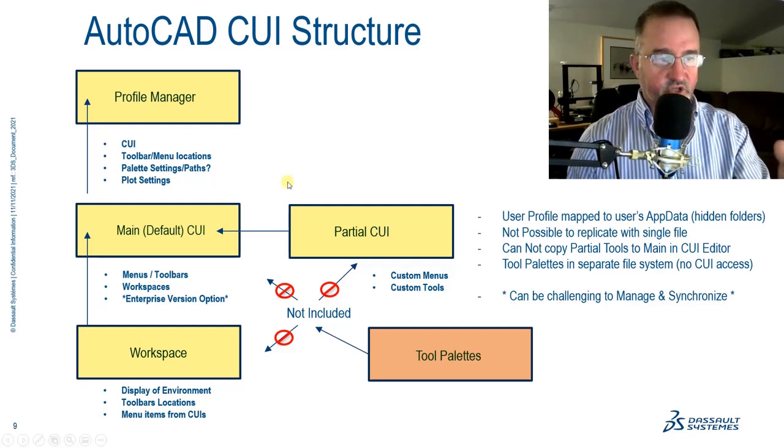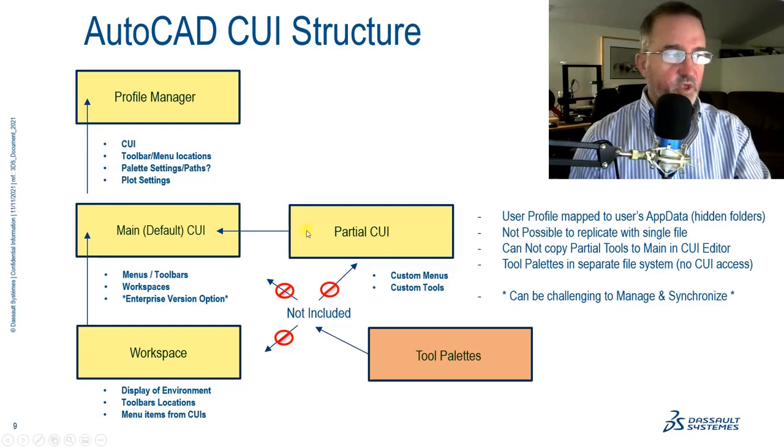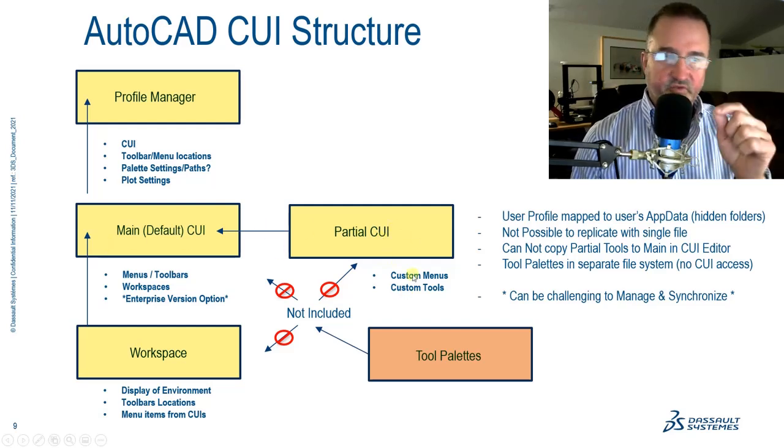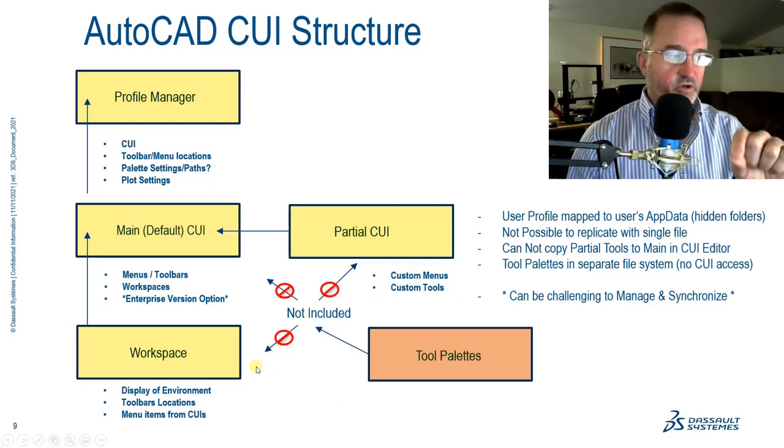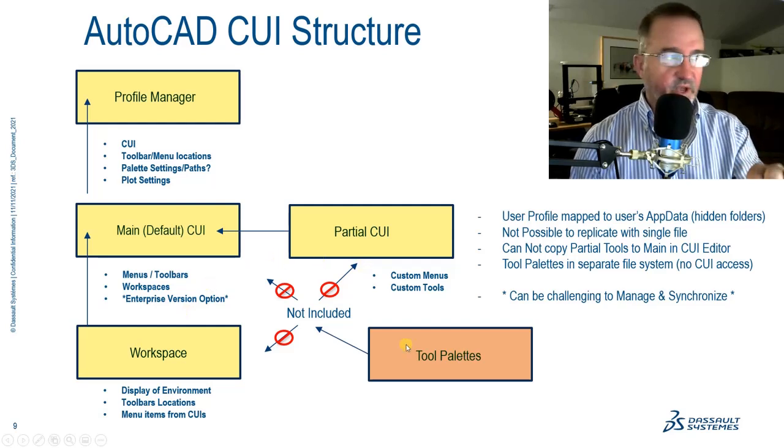And what's a challenge with this is where we do our customization is typically around the partial CUI. It's hard to move things. You can't move things from a partial CUI to a main CUI. And also the CUI contains a workspace, but it doesn't contain the tool palettes.